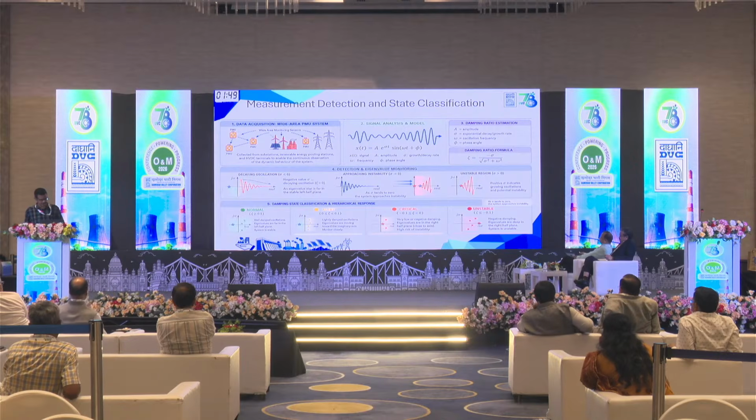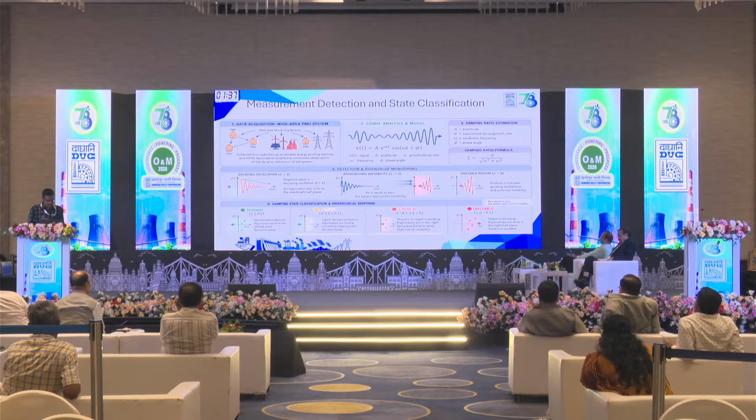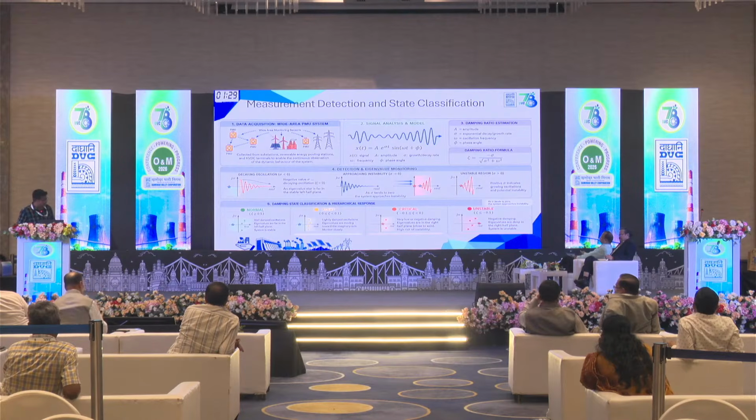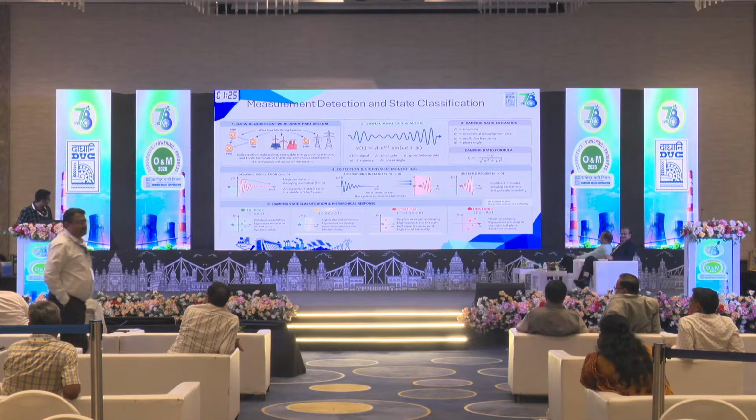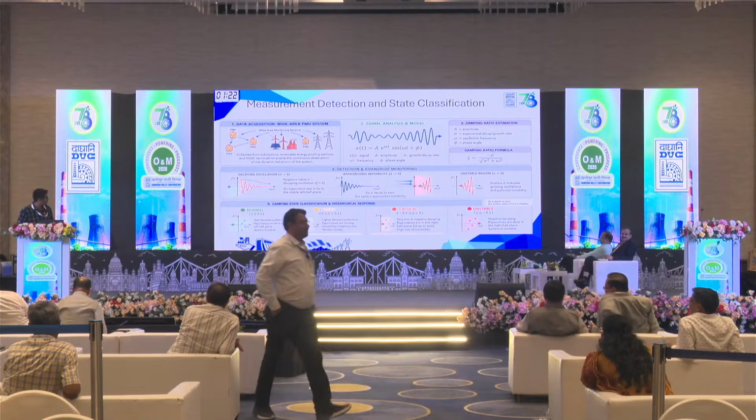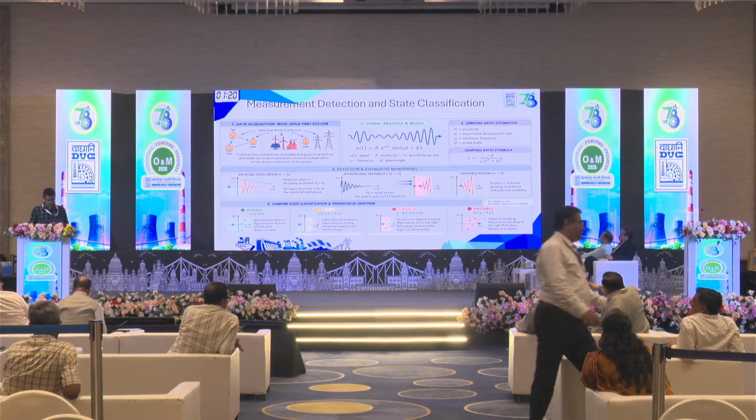Measurement, detection and state classification. In this, OMS works on a wide area measurement system and signal analysis of oscillation modes. It also calculates the damping ratio of the system, and by calculating the damping ratio, it gives a hierarchy like normal, alert, critical, and unstable.